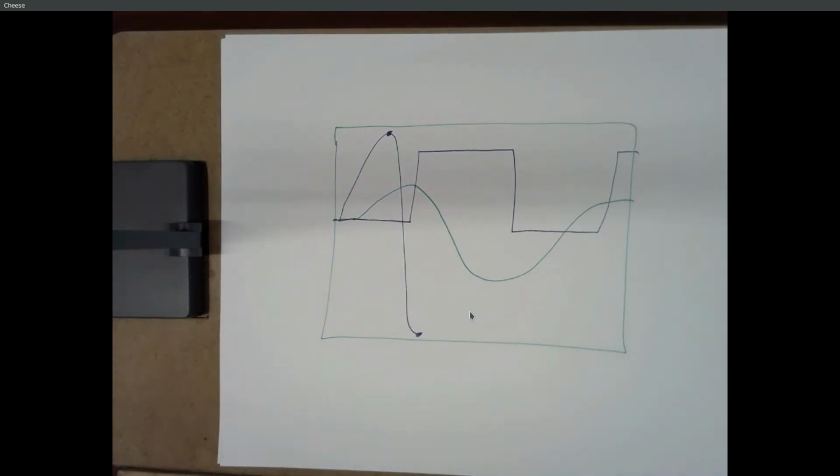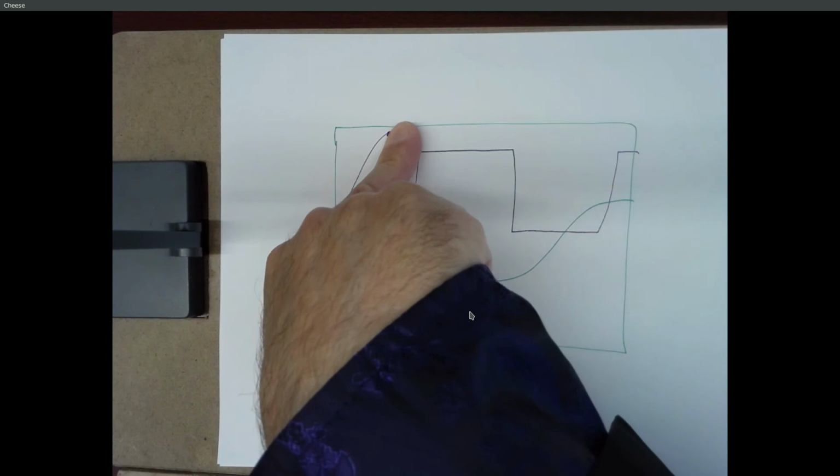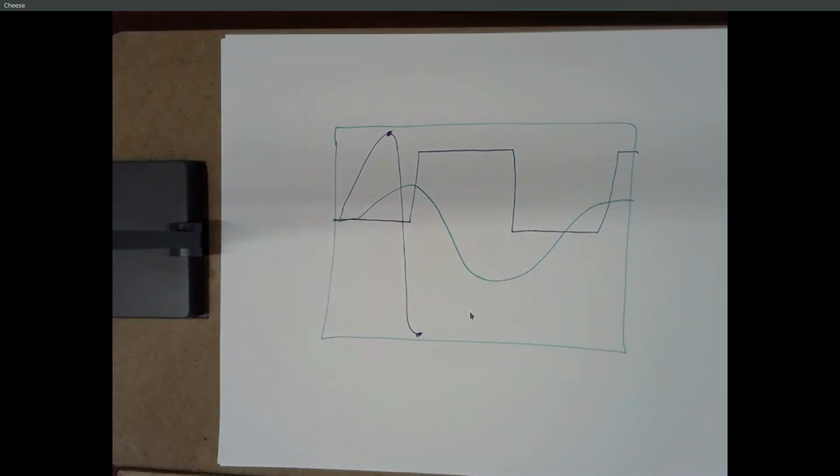So the oscilloscope will let you adjust the frequency and the amplitude and the DC offset so that you can look at your waveform however you want to see it. Now the dirty secret is there's a button on top called Auto, and if you press that, it kind of does all this for you. And I didn't even know it. I saw some students doing it once, and I'm like, whoa, that's cool. But that's what's going on inside, okay?